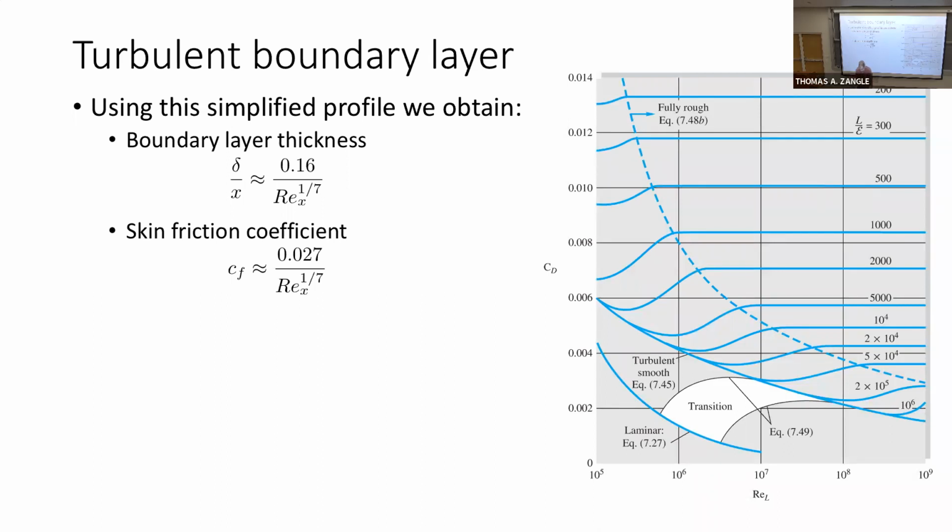And then I would end up estimating the coefficient of drag, which would be uppercase C_D, right? But with a boundary layer flow like this, the flow changes as we move downstream, because the boundary layer is growing. In this case, we'd see the boundary layer initially laminar and then transition to turbulence. This table's a little rough, so we'd get that transition probably pretty early, right?